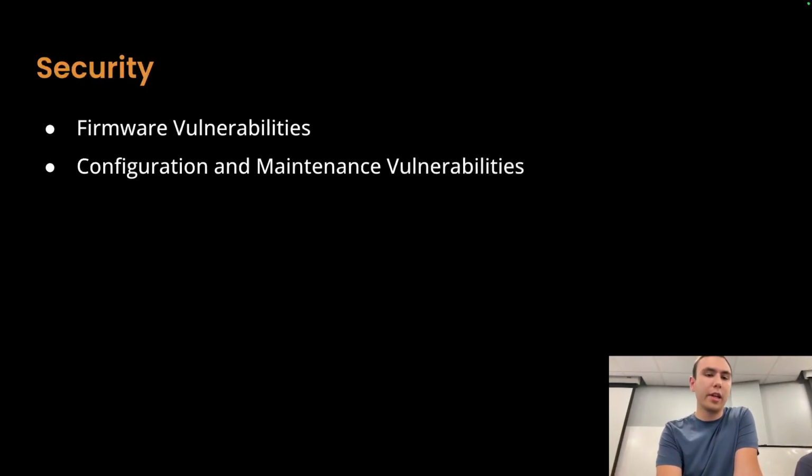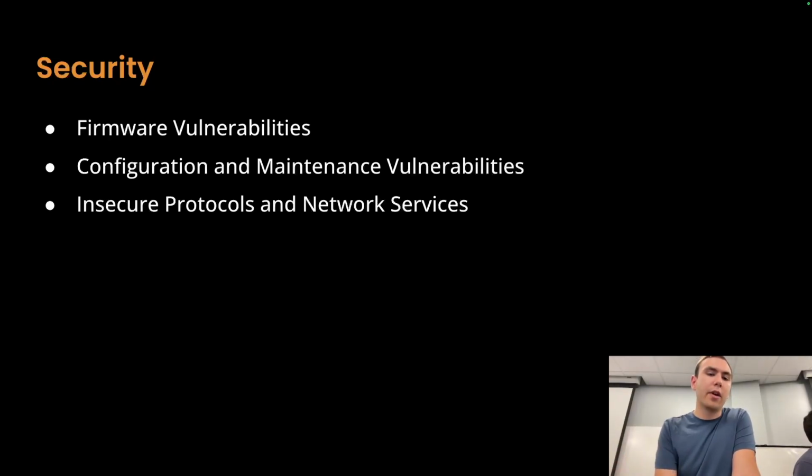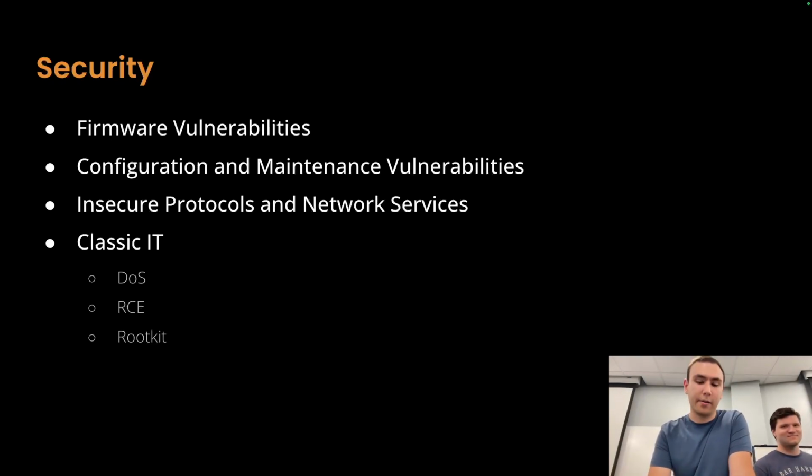Now, when talking about security with PLCs, it's a big one. You've got firmware vulnerabilities. You can also have configuration and maintenance vulnerabilities. If in your program you have the normal bugs like in any other program, somebody can exploit that if they know what inputs to send it. Additionally, you have the insecure protocols and network services that it uses. But then you also have classic IT stuff, like you can denial-of-service it, get remote code execution on it, or give it a rootkit, like everyone seems to do with PLCs.